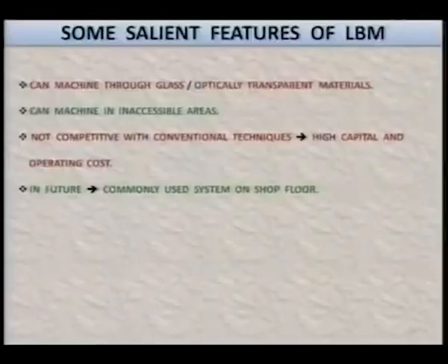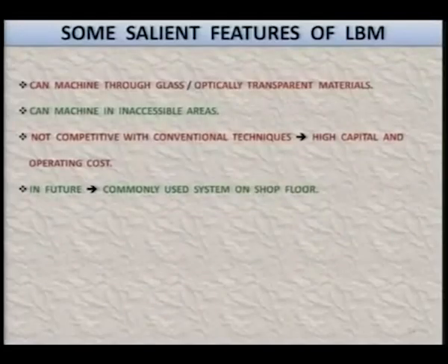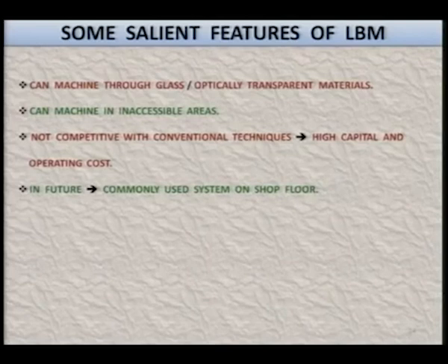So, because laser beam machining machines are high capital intensive and also the operating cost is very high. One can imagine that the efficiency of the laser beam machining system is lower than 1%. So, you can think of how much the operating cost is going to be.